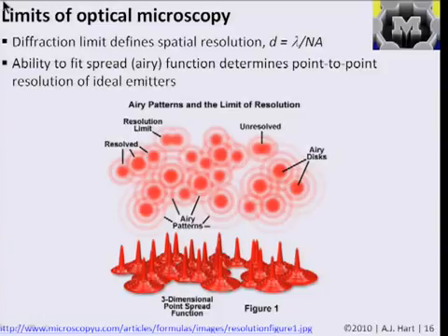So by changing the characteristics of the lens, you can, for example, slightly beat the limit, and that's used in advanced lithography to slightly push this limit down. And another way to look at it is the ability to differentiate between two points. Imagine that you have two points emitting light, sort of ideal delta functions. They will have a function of emission that looks like that, called an Airy function, and the ability to resolve the location of those two points is sort of the minimum distance that you can measure.